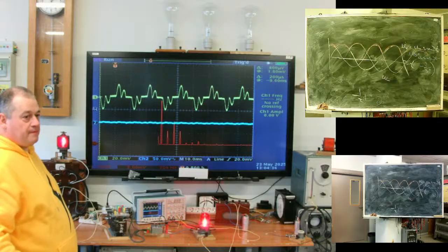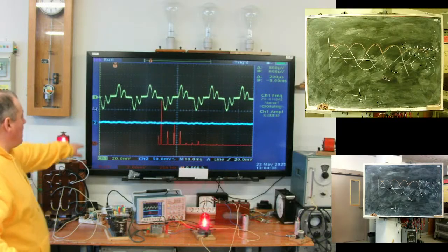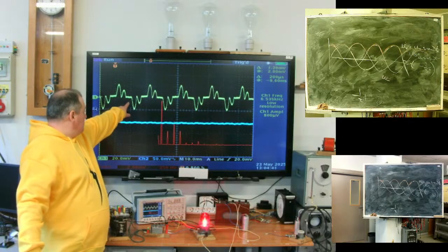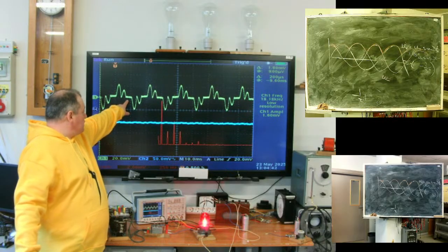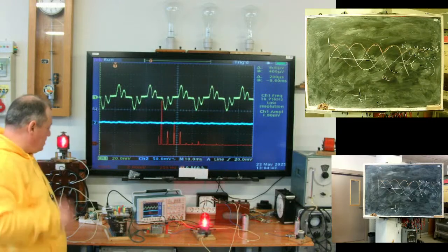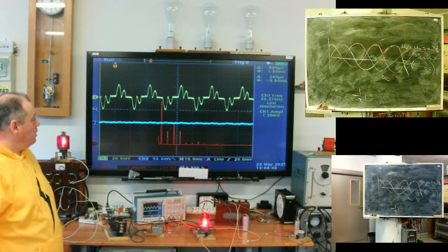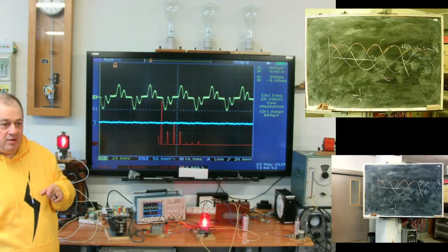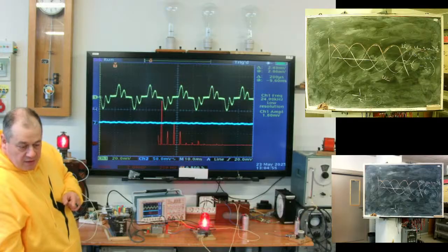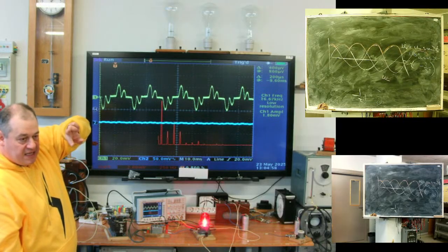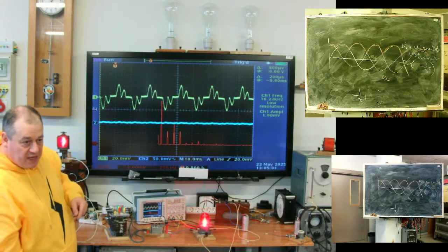It will be like DC. At load side, you see a nice DC line. You see what happens on the primary side? Not one nice peak, but two. Because we will see current AB, AC, AB, AC for A phase.